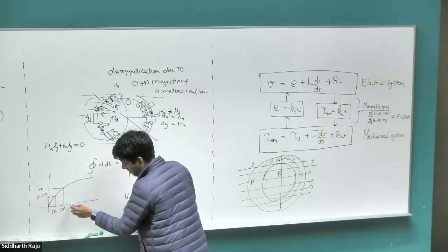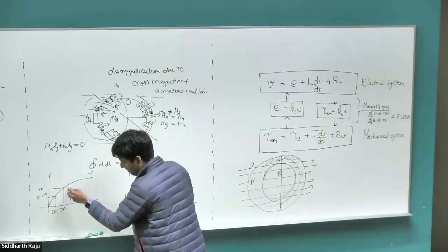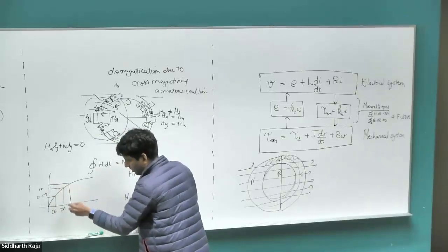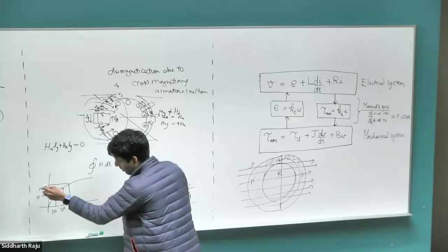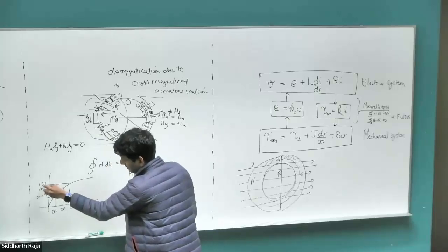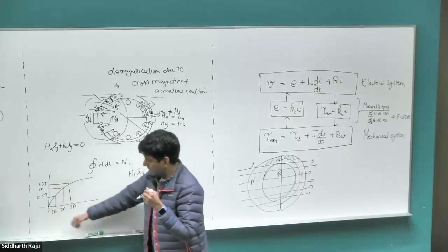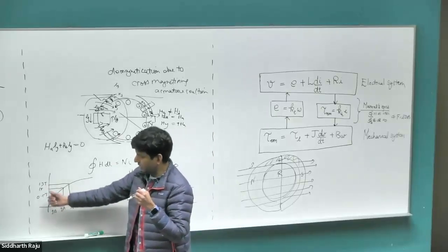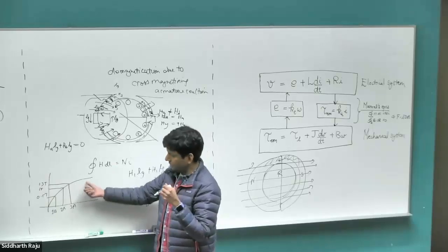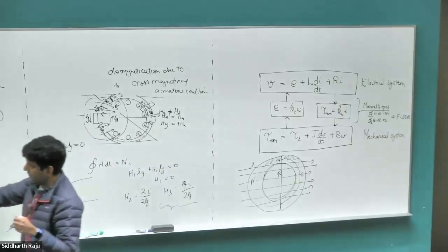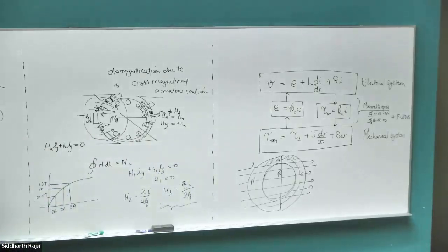But then if I apply 3 times, it won't go to, unfortunately, 1.5 Tesla, but it will go to 1.3 Tesla. Right? So this is what saturation effectively is. You can add more current to it, but it does not linearly increase. Once we enter the saturation region, we cannot directly just sum these waveforms together. So the net magnetic field is just not the sum of 2 magnetic fields alone.